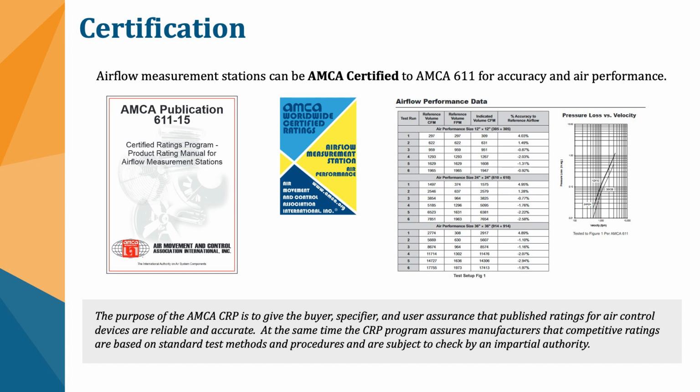The sizes aren't quite the same. You can test what sizes you want. Now, the sizes that you test will cover a certain area. It's kind of like UL rated, fire rated dampers. There's going to be a limit to what you can test. And you can certainly build airflow measuring probes and stations that are bigger than what standard AMCA 500 ductwork can be set up for. So you really are only testing representation of the area that you're covering with this unit.